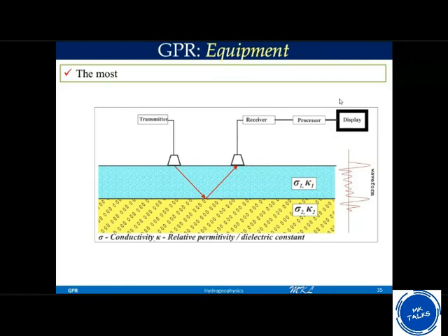You will be defining some parameters, and according to those parameters, you will be taking the data. I'll be explaining GPR in detail because these things might be very helpful for your research in the near future. So try to understand this. For the received waveform, there is a dielectric constant of air and this blue first layer. Air and the first layer give you this peak, and there will be a dielectric constant contrast here that gives another peak. This is how the GPR signals look when recorded.